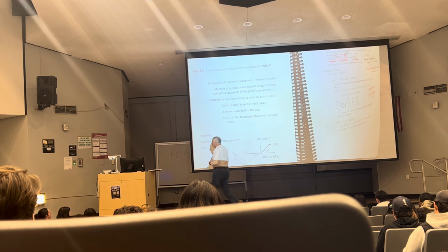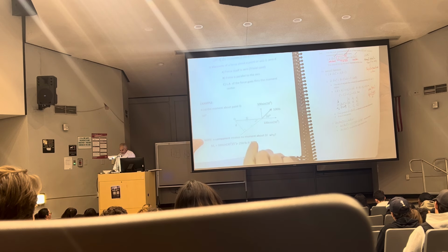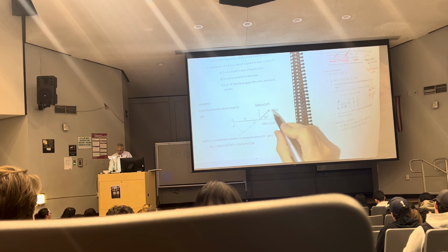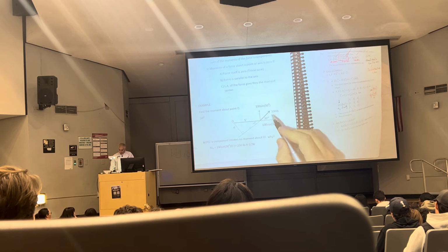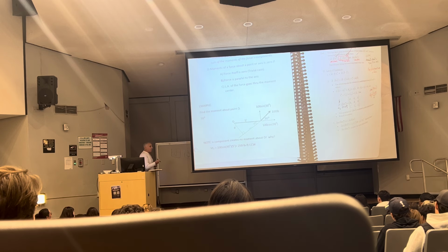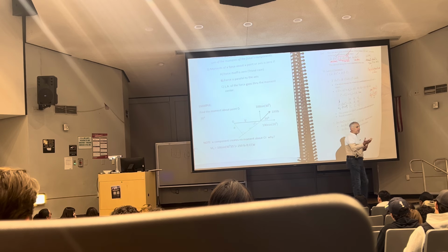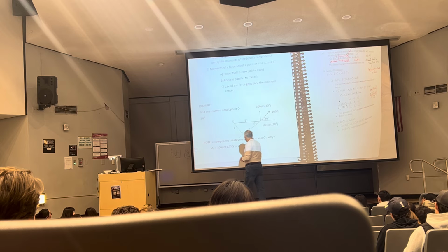I'll give you an example of basically these two in action, Varignon's theorem and transmissibility. So I have this force of 100 pounds. I want to know what the moment is over here at O. Great. If I don't use the components, then I need to take this force and find the perpendicular distance from the line of action of the force to O. That's just geometry, trig, whatever it takes to find angles and distances. Usually it's SOHCAHTOA, right? Because usually you have the right triangle.